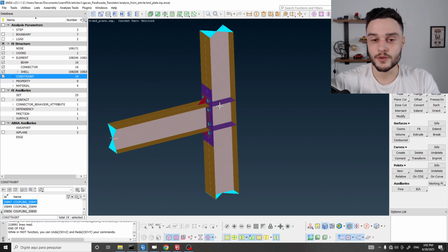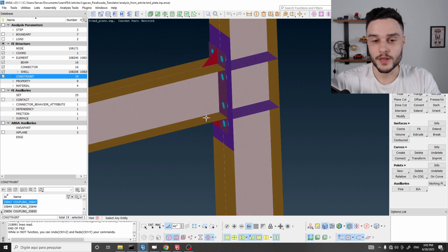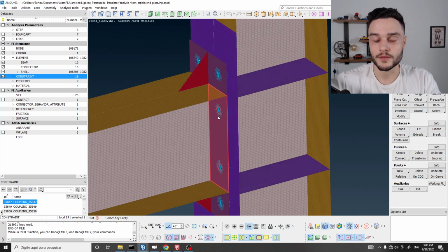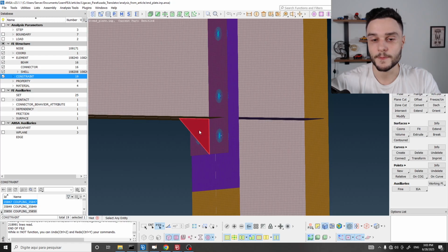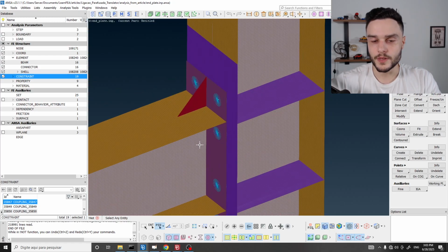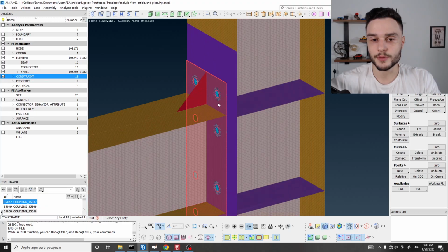And to connect these 2 entities, we can use many types of connections. And one of these types is one named end plate. In this kind, we weld this plate that you see here at the end of the beam. We can have stiffeners, which are these triangles. And then we connect this plate to the column through bolts.